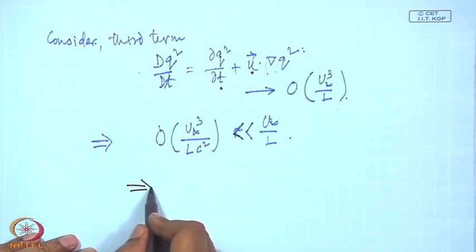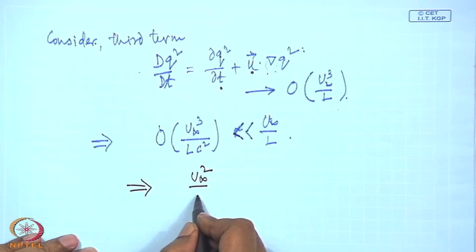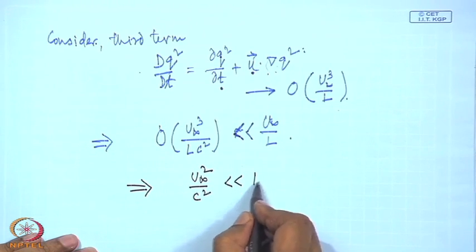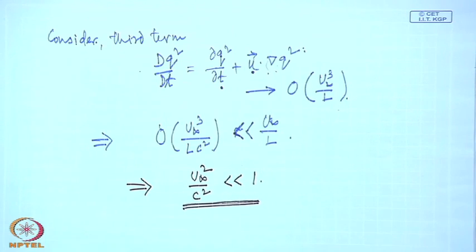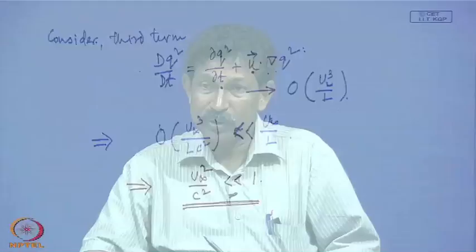So, this is one of the conditions. In particular, think about a flow in which the body force has not much influence and the flow itself is steady, with no time change. Out of these three, if the body force has no significance, this term we need not consider. Body force is not present or is insignificant, meaning that we need not even worry about this term. If the problem is a steady problem, this term also has no meaning.